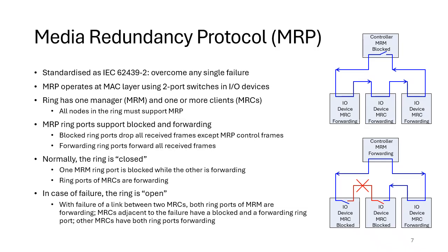You could do it if you wanted to extend the network. For example, you might want to go on a copper cable network between 2 devices, and it might be more than 100 meters. So you could use a switch like a repeater. But you are exposing the network to additional failures. And if that non-MRP switch did fail, then all you would notice is the same effect as if that piece of cable had failed or was unplugged. So it's not strictly true that all nodes in the ring must support MRP, but it's good practice that they do all support MRP.